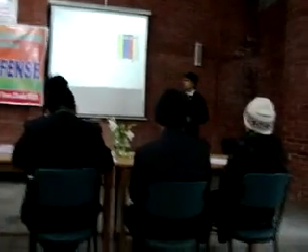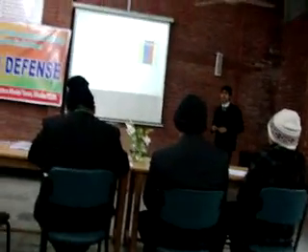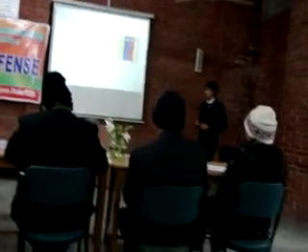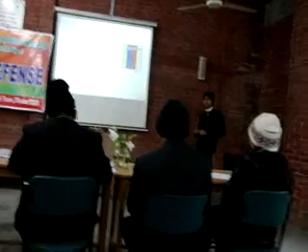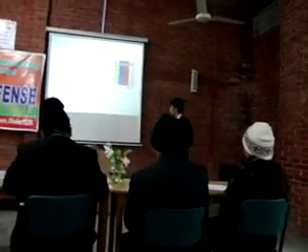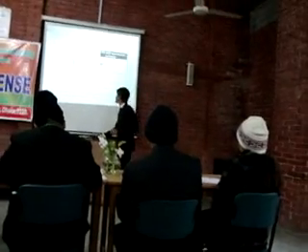This is the power supply. We supply DC power to the PLC, to the processor and modules. I use the TSX Micro 3722 PLC. This PLC takes 24 volt DC power from this power supply.